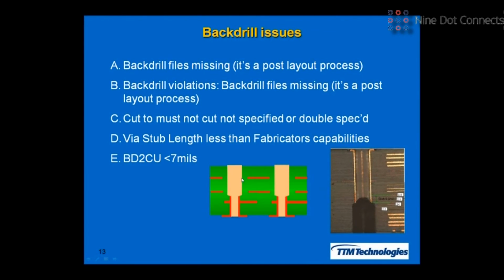But in the field, if you're inside of a server closet somewhere on the equator and you've got 80% humidity and, you know, fans going and it's really hot in there, if this plane was really close down here at the bottom, you could get some sort of a fungal growth and maybe electrical chemical migration shooting across there, where it would develop into a short. And they've actually had some documented cases where this has happened.